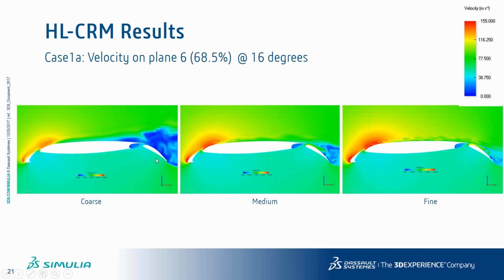Okay, that makes a huge difference in the mechanism of the flow, and will induce a large separation on the flap. Okay, that doesn't occur as soon as you refine in these regions, probably because you allow the flow to pass better and evacuate through the gap in between those two elements. Okay, so you've got the effectiveness of the high lift device better modeled in this case.